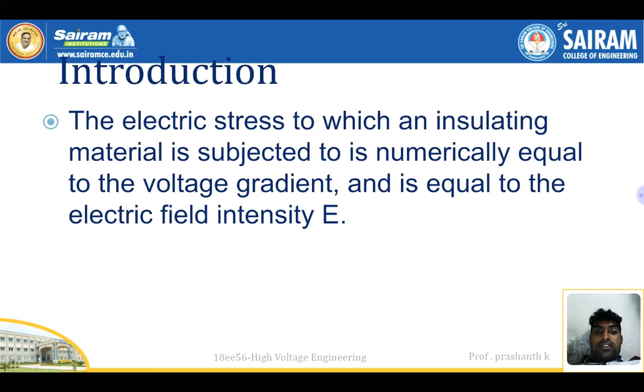The electric stress to which an insulating material is subjected is numerically equal to the voltage gradient and is equal to the electric field intensity. Electric field intensity is the force or stress created inside whatever the media. And also we have a number of insulating materials, classes like Y, A, E, B, and so on.